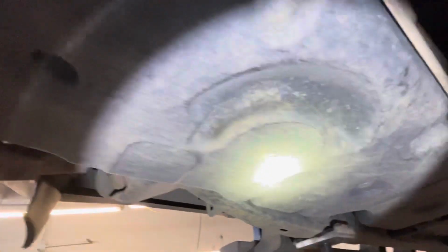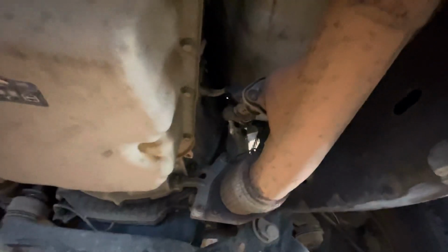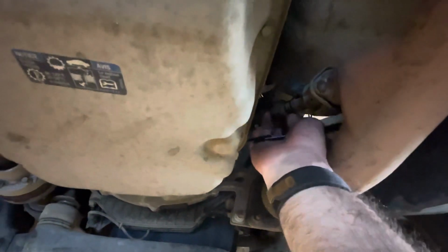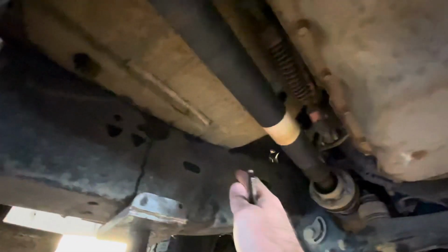Okay, check it out. There's the exhaust fluid tank up above the spare tire behind the rear axle. We've got hoses right there that run along the frame. Up along the frame. I think that we come up over the engine and then we come over to this side where the exhaust fluid injector is, okay? So I don't know if you noticed, but there were no signs of exhaust fluid leaks anywhere. There's no crystallization here. There's nothing on the frame. There's water here, but I determined that that's from the air conditioning. So nothing to worry about there.